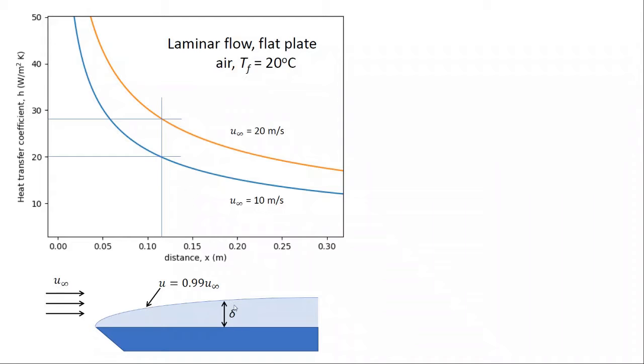Now, likewise, we have a thermal boundary layer, which we know doesn't have to be the same thickness as the velocity boundary layer. And before we said that the thickness of those two layers was related by the ratio of the ability of momentum to diffuse to the ability of thermal energy to diffuse, and that was given by the Prandtl number. And so the Prandtl number to the 1/3 power largely gave us the ratio of the thicknesses of the velocity to the thermal boundary layer.